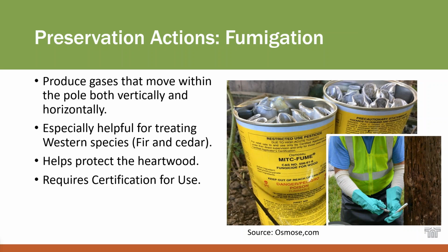So once you find the rot, you have some opportunities for preservation. I'm going to run through a few slides of preservation before we get into the repair. This one here is fumigation. When the timber is originally installed, it has that preservative treatment around the outside. That works great, especially if you're going to replace these bridges on a normal time cycle. But a lot of these bridges are well over 50 years old. If you hammer timber into the ground or leave it exposed to weather, it's just going to rot. That original treatment is not going to hold up over time.